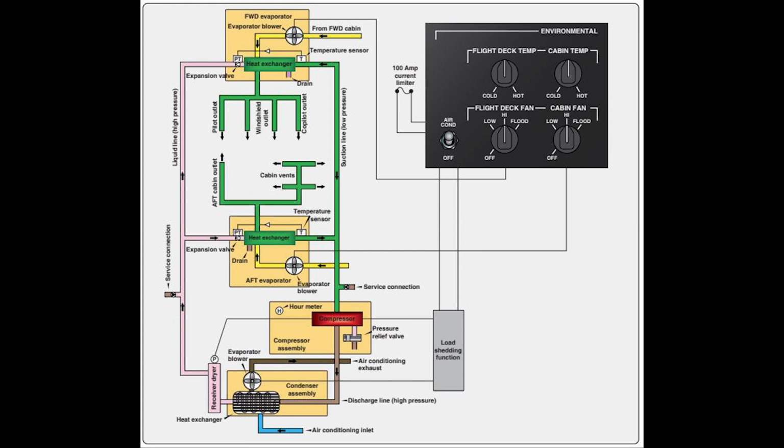Like I've worked on a Cessna 206 that has an air conditioner on there. The reason they have air conditioners is because you don't have any of that support, and if you're going to try to get in the aircraft and cool it down, especially if it has a lot of avionics in it, you're going to want something that's probably separated from the engine, that you could turn on with just electric power and run just like you would an air conditioner at your house, and that's where these start to come in. That being said, you generally won't work on them a whole lot unless you're in that world.